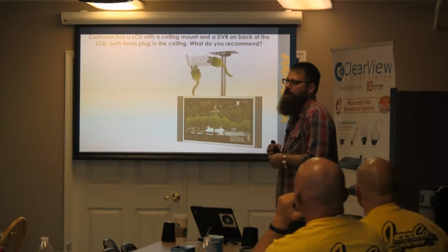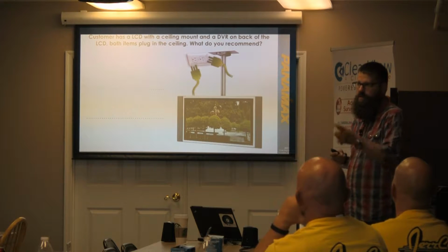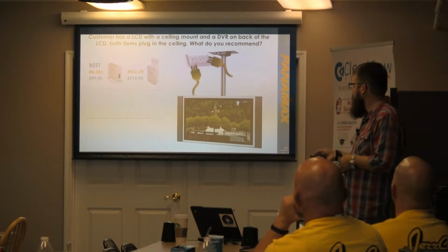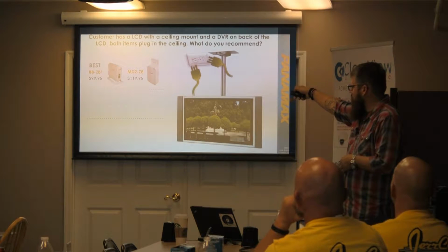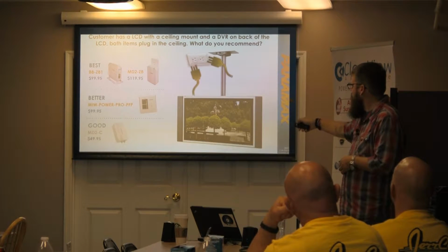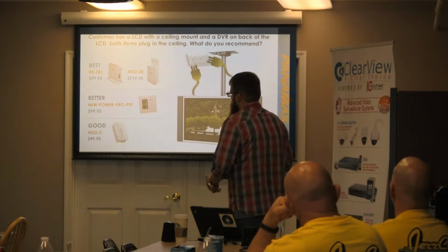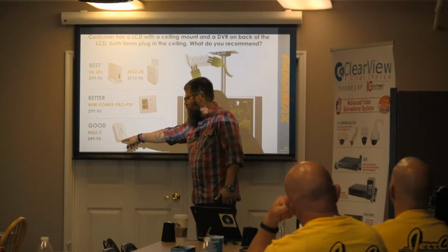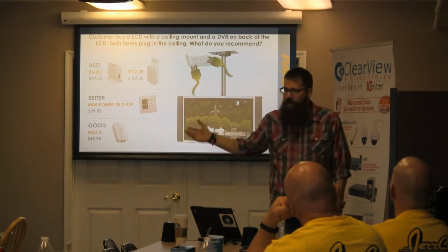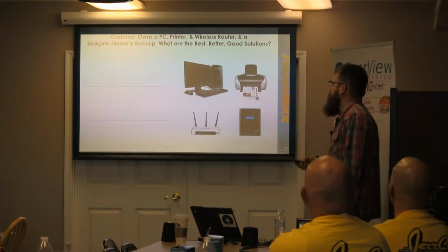Just for voltage, you just change out the outlet. Right, do the outlet. There's a couple of different options. You could just do the Decora outlet as voltage. You could do this guy. We'll talk about this later because this is Bluebolt. Use a 2-gang recessed outlet, switch that out. The outlet like he said, or just do the modular piece, because this will give us coax as well. The DVR's on the back, so you can run the coax in and the 2 plugs and get protection. It's a $50 solution, retail. This is a no-brainer here.